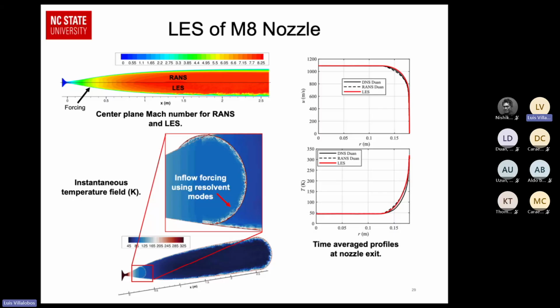So that's why I was wondering whether it's also because of the behavior there. Something like that, could be. Certainly it's correlated with the RANS model's behavior; we just didn't get this great. Yeah, and we shut it off. And the RANS model in this case, is it some SA variant for hypersonic? No, this was Menter SST VSL. I think we tried Menter, both of them with some transition trick.